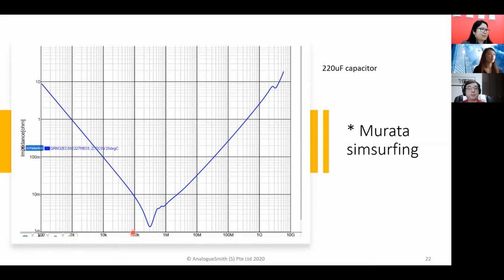So here's 100K and there's a megahertz, right? So you can see at low frequency, we have a capacitor, right? With a capacitor, the effective impedance decreases with frequency. Okay, so as the frequency goes up, our impedance is going down. And then at some point we just drop. And then we come up again and we start going up the other side.